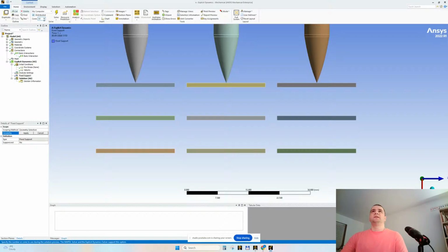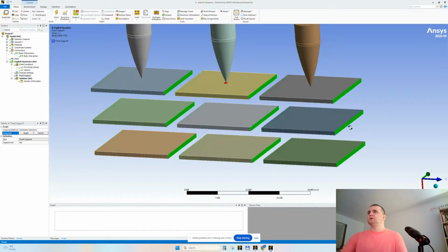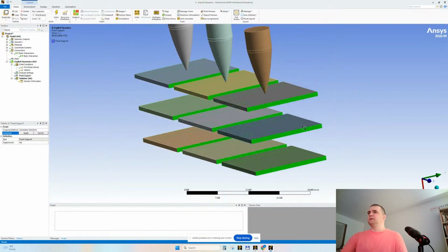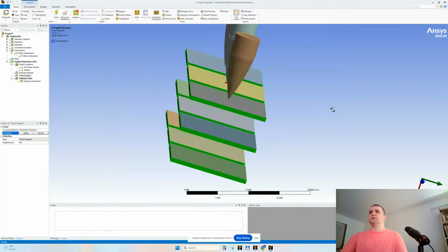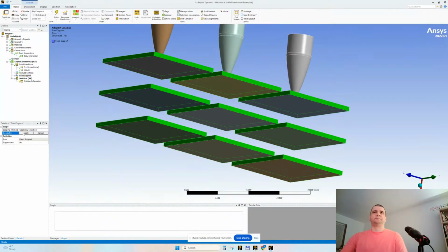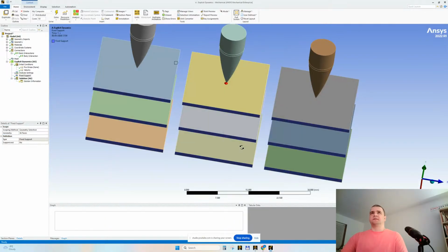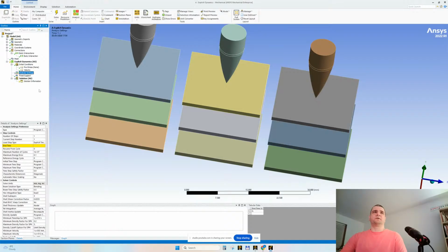Please look, I put mine here, I customize it. Please look for the box select somewhere, or in the middle mouse, or in the selection. You need to be on the box select, and you have something like this. With Control pressed, we select these faces, and you can see, yes, they're selected. Also, we will reposition them like this. I'm clicking the Z axis again with middle mouse and Control. Look, everything is selected. Apply. They are fixed. We have the initial velocity perfect now.